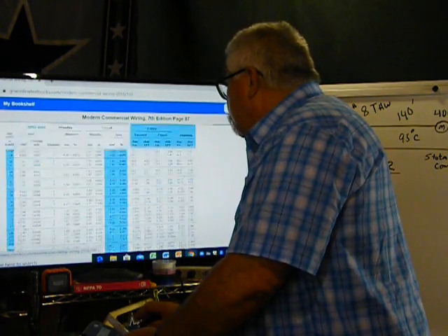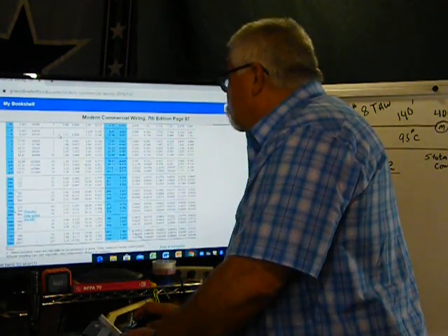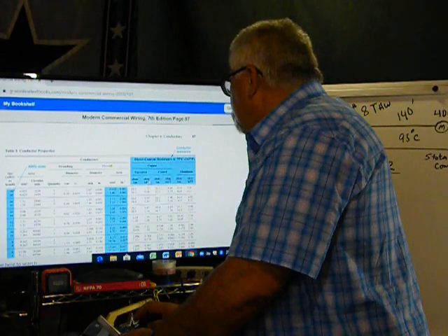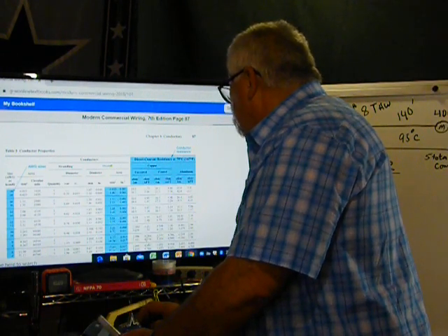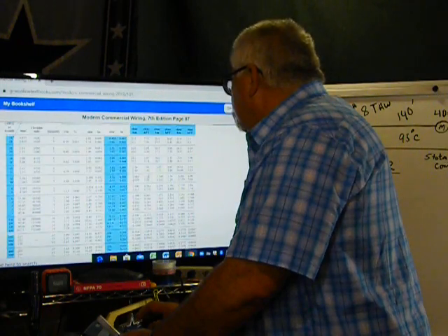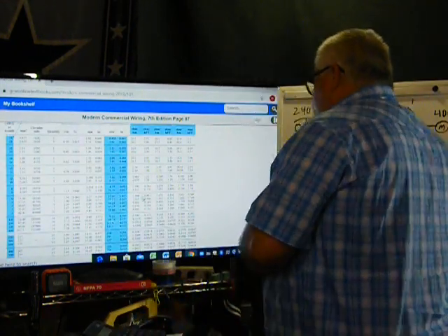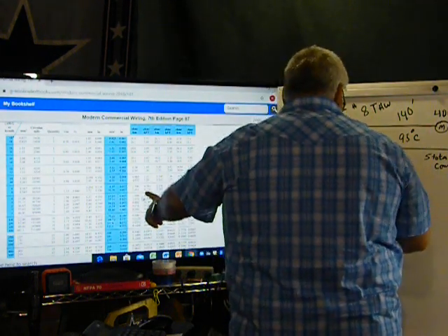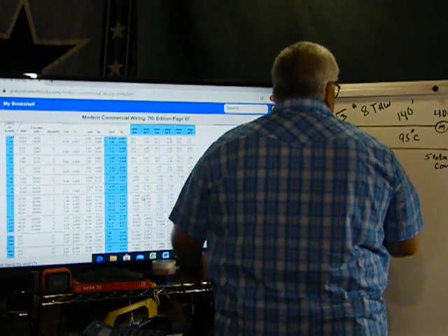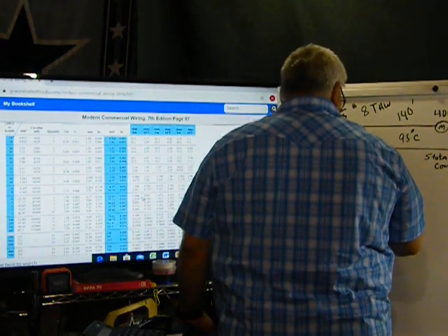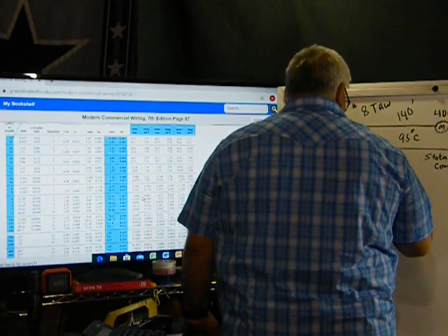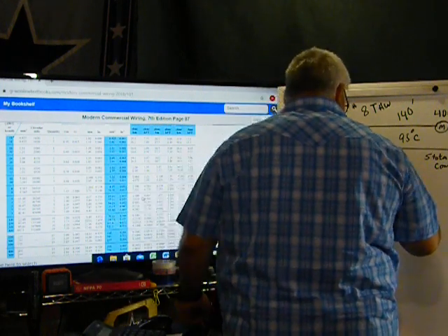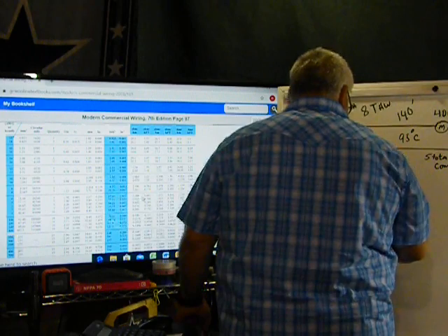Table 8. Okay. And the reason I use this, now we got to use that stranded, coated copper, uncoated copper, number 8. Did I pass it up? Number 8, uncoated copper. And then this number, so it would be 2 times 140 times 40 times my resistance. My resistance is 0.778 divided by 1,000.